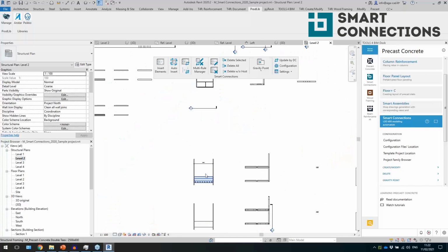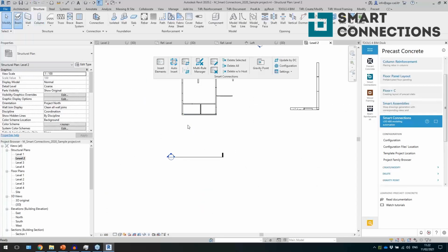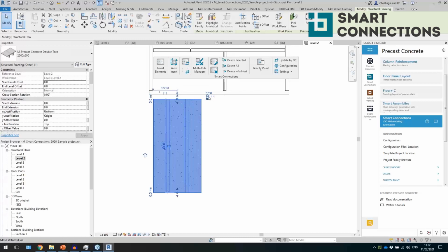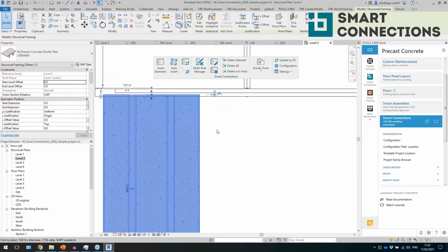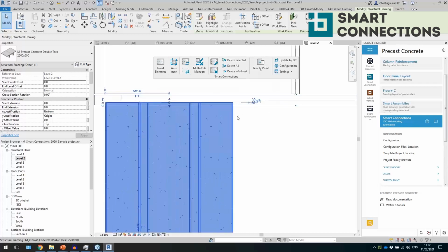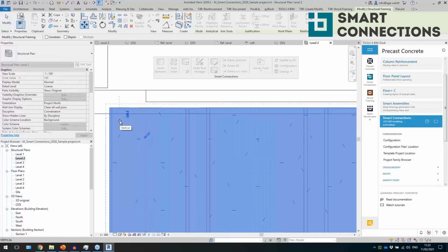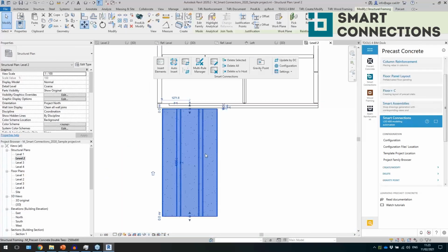And if I will draw a couple of elements here, so structure, beam, and I will show you a little bit. All right, so let's change the end offset here from the wall. Oops, it's not from the wall. Sorry about that. Let's just move this one a little bit, like 100. Okay, so it was from the cut actually, but not a big deal.